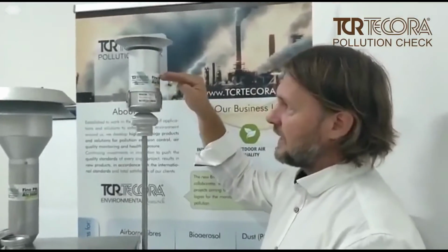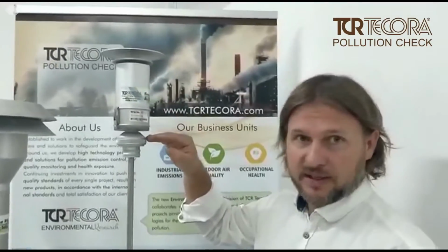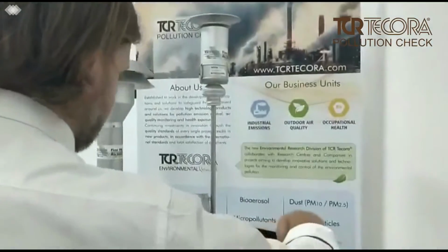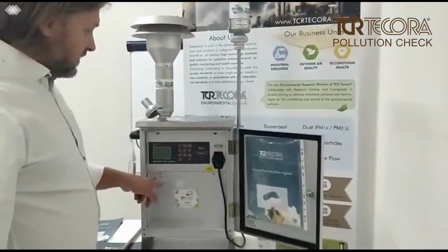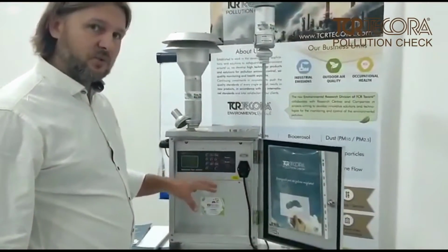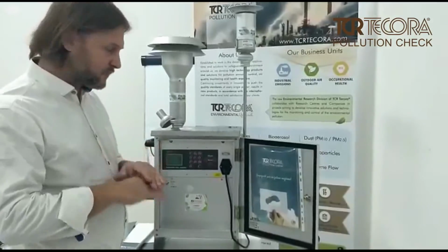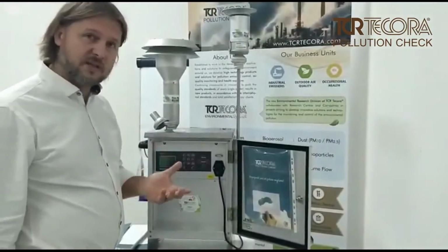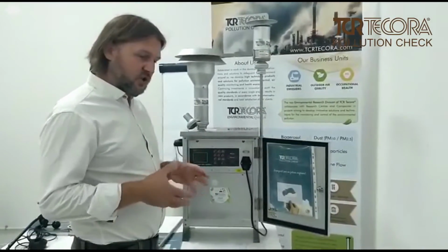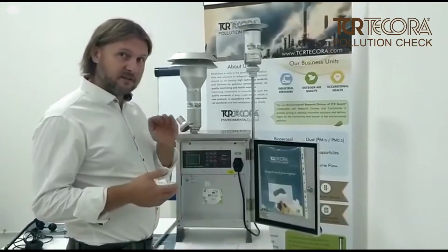Here we have the cut sizes for the dust, the membrane where we can collect the fraction that we cut, and then this is the sampling tube that goes deep inside the instrument. Inside the instrument we have an automatic system that is able to measure the flow and to control the pump in order to keep the set flow stable. The system that we use is a frequency converter that drives the pump and changes its rotation speed in order to maintain the set flow.